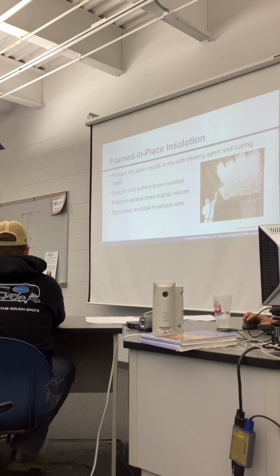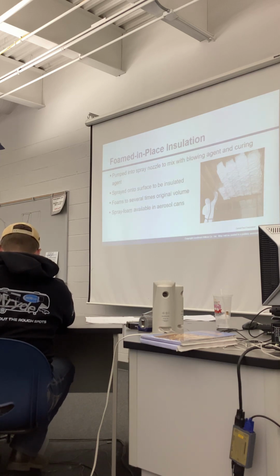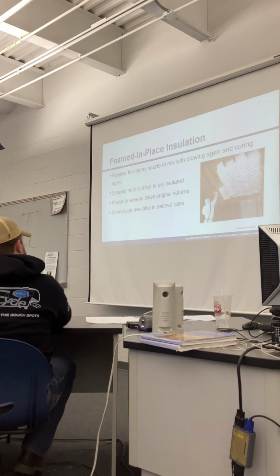Foam. All right. Foam is a great product, used in the right location. It can be overkill, since it is a vapor barrier and an insulation in one. Remember what I just told you about spraying the ceiling or putting plastic on the ceiling and putting plastic on the walls. If you use this incorrectly, you can seal your house up so much that you have the same problem with having a vapor barrier and everything.